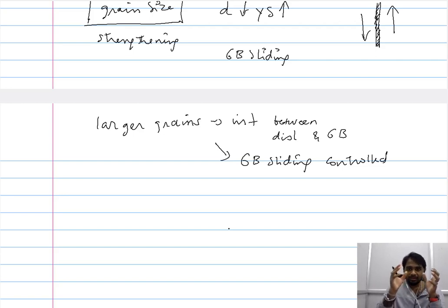So with this, we have considered three different ways of enhancing the creep resistance of the material. One involves solid solution strengthening, the other involves introducing a second phase, and finally working on the average grain size of the materials. So by thoughtful consideration of these three parameters, we will be able to enhance the creep resistance of the material. So to compile it all, we have seen high temperature materials, what it means when we say high temperature application.